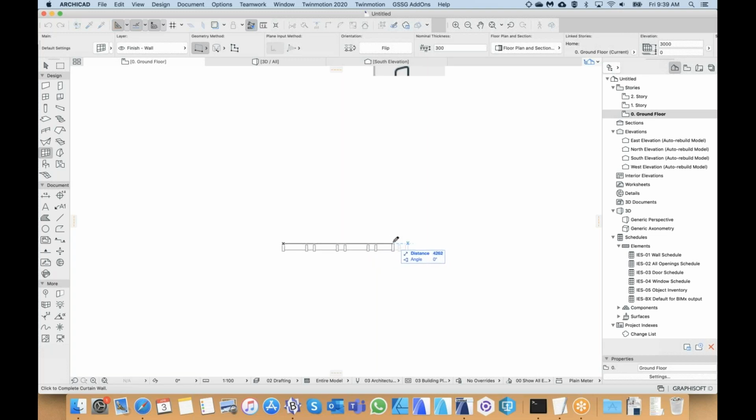So where is the next pattern going to finish? And because I see that preview, I can snap to that preview, so I can snap exactly to the correct sizes. But if I just choose a random size that doesn't snap, then it's going to cut off the pattern. Okay. So I'm just going to click where I didn't snap on the end, so I just put part of a pattern at the end.